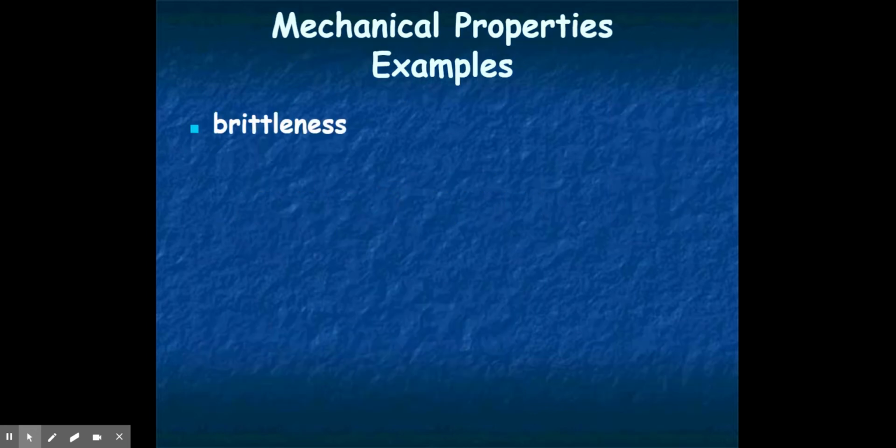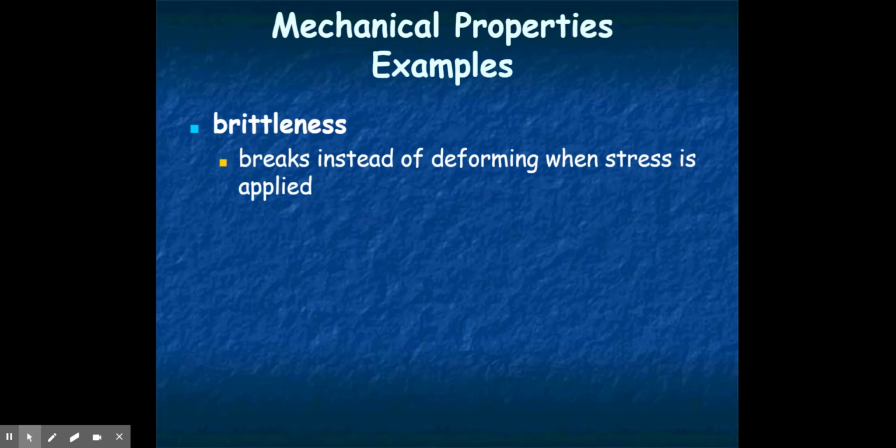So the opposite of that is brittleness. Brittleness is a piece of chalk snapping in two, something that's not going to hold together when hit or stressed. It's not going to bend. It's going to just break. Now it could be hard, and we could talk about hardness, which we will. But it can be hard, but at the point where it starts to deform, it doesn't have much deformation ability in it. It just snaps. So it fails rather catastrophically.